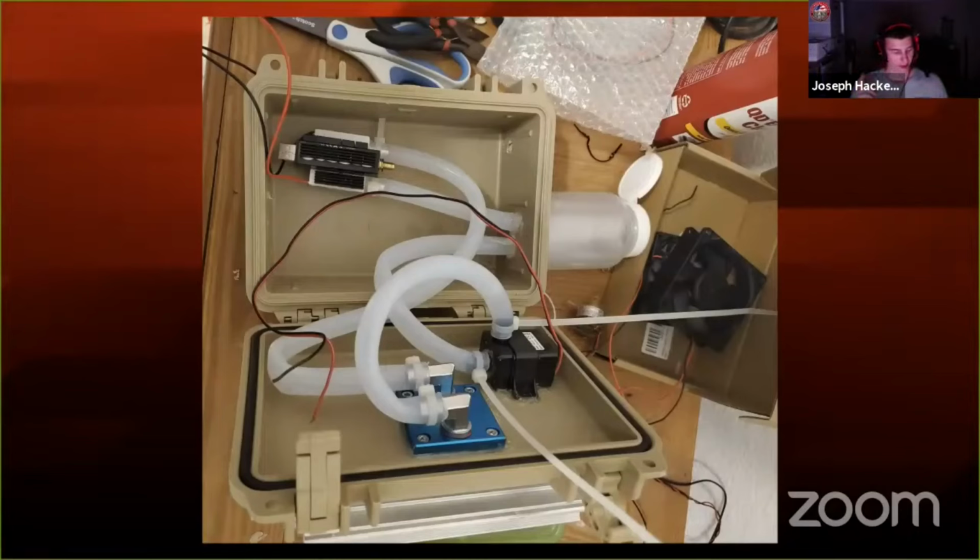But water cooling your electronics, and this brings me to the other stuff, not just this particular application. You could do something similar for a ham radio. A lot of these ham radios now, especially the 2-meter radios, generate a lot of heat. Most of them have a fan on them now, but they still get quite hot. If you're having issues with heat, maybe something like this might work. You could have one of these aluminum blocks on the outside of the case and attach that with some thermal glue, or even just thermal sticky pads, so it's not a permanent thing. That'll probably help transfer a lot of your heat away.